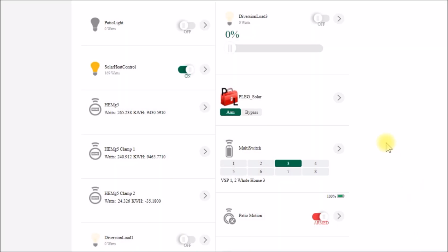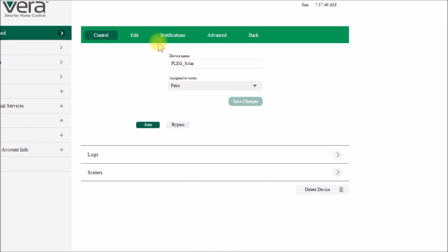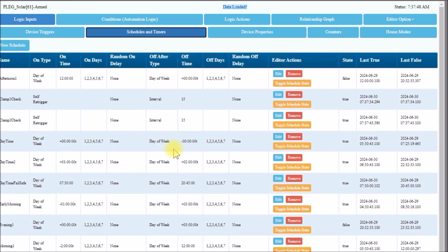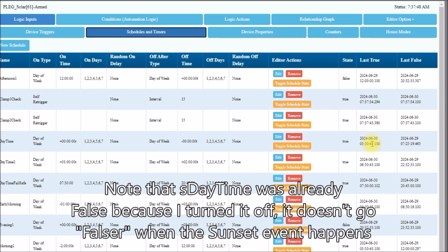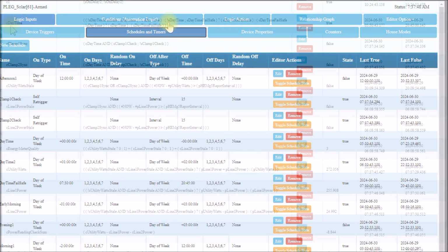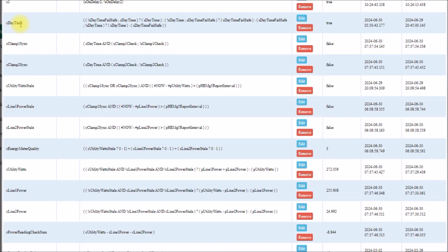Okay, so this is the following morning here. Yesterday I had turned off the daytime schedule, and now today it started up normally here. Fired at 5:50 this morning, and this was when I turned it off yesterday at 7:25 in the morning. So that stayed there, and the fail-safe timer turned on at 7:30, and it turned off at 8:45, just like it's supposed to.